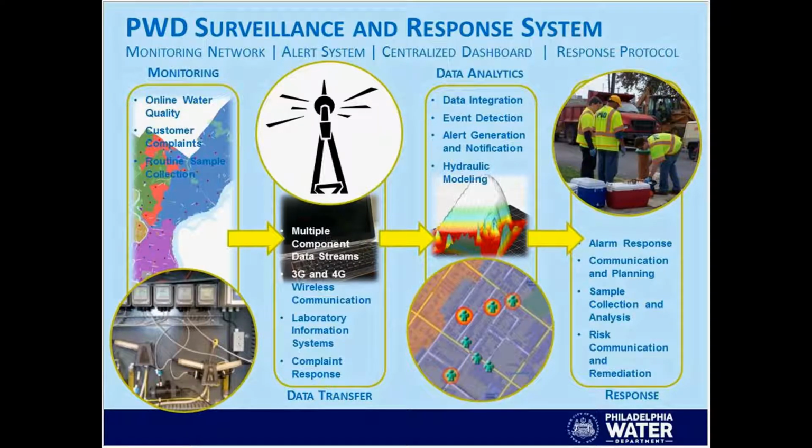However, on the front end, I want to point out that developing the protocol for your data and communications should really be established at this point on the front end, because at the point of data transfer, when it's going from the online system into the event detection system or the water data management system, having the data protocol established on the front end really drives downstream software and hardware requirements. And so you don't want to constantly be changing your protocol.